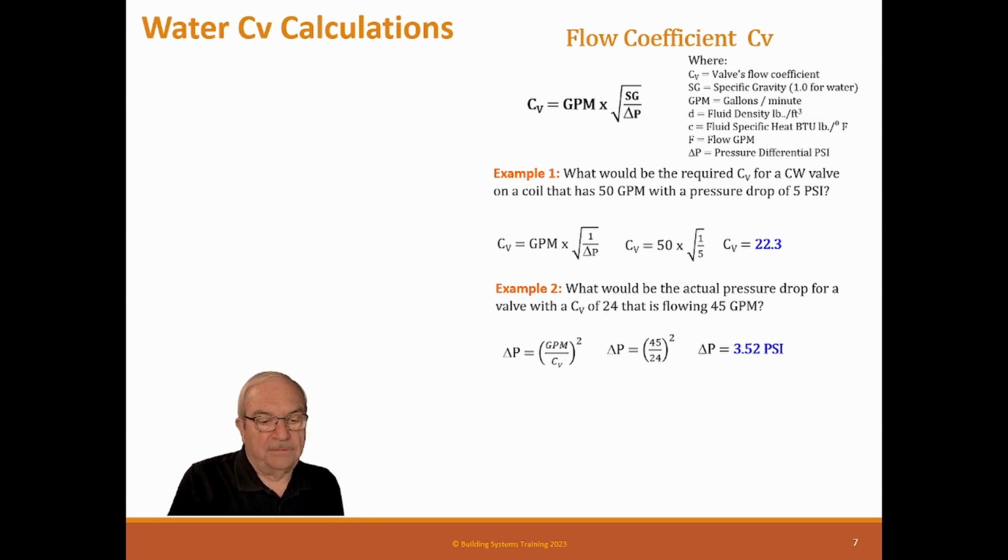And then when you went to the flow of the reheat coils, we're way under that. So to balance the job, you had to be almost at close, 100% close. So that doesn't work. The balance valve should have a reduced port in it so that it has some range of controllability to actually provide balance to the system.